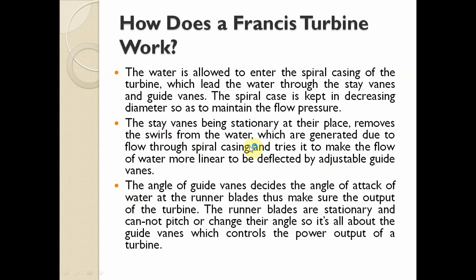The stay vanes, being stationary, remove the swirls from the water which are generated due to the flow through the spiral casing, and try to make the flow of water more linear before it is deflected by the adjustable guide vanes.